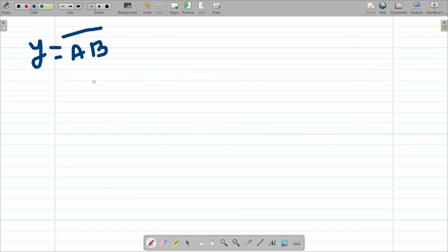So what I have said, we have to start with the pull down devices. To connect the pull down devices, we have to see how the expression is. So in pull down, NMOS devices will come. Here, every variable is one device. So A is one device, B is another device. Two devices are there. So in pull down, we need two NMOSs because NMOS devices will be there in pull down section.